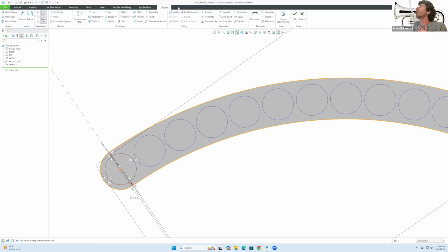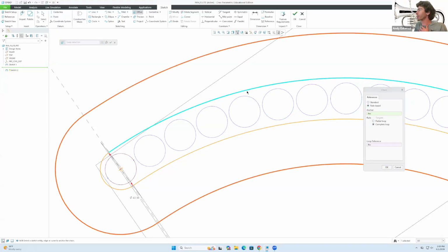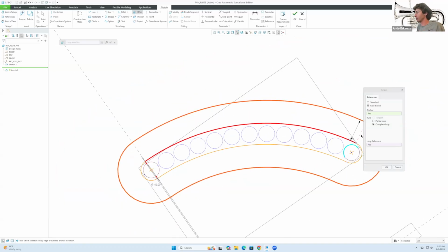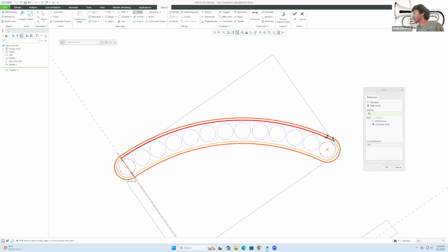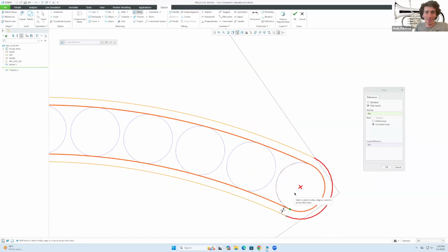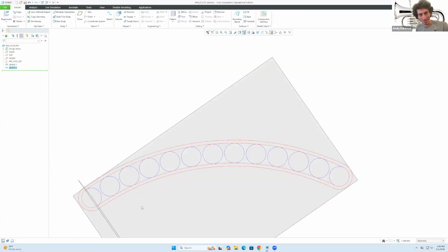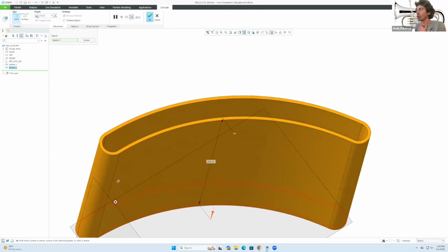But we are almost done, because one last item that I would like to do is that I'm gonna go all the way to my friend now, the offset. I'm gonna now select the complete loop, and I want to offset inwards by -5. So now they're all gonna be tangent like that. So I'm gonna click on OK. And now finish. So this banana shaped piece in here is gonna actually be one of the first things that I'm gonna CAD. So I'll go here to extrusion.